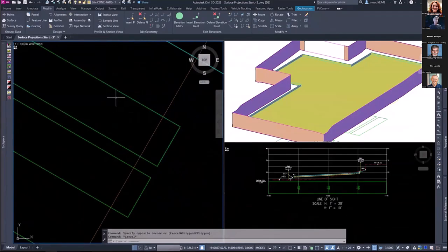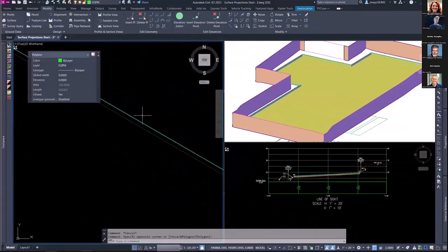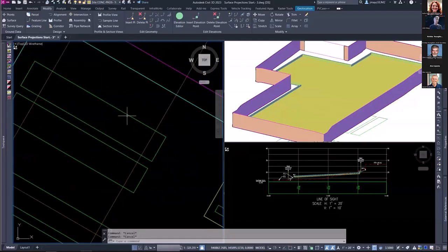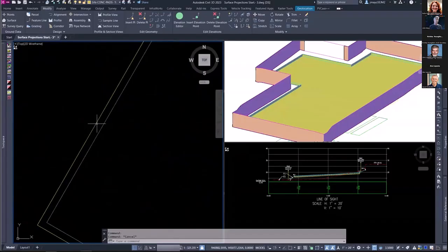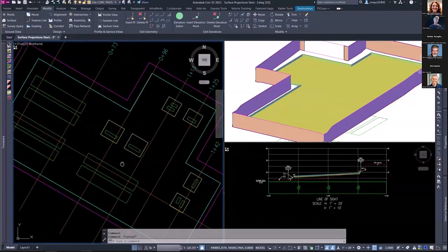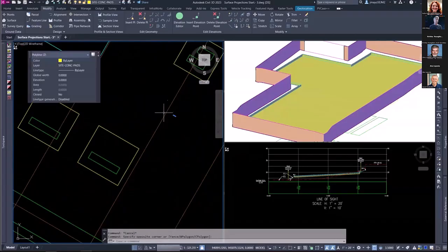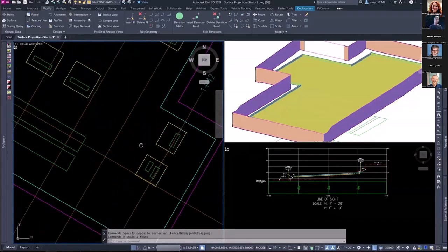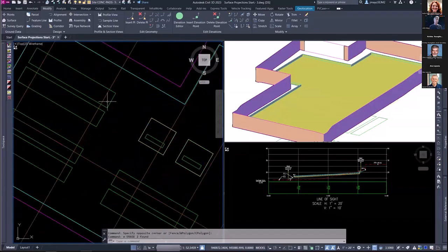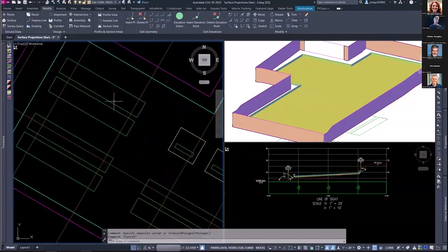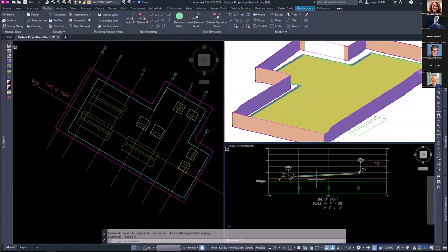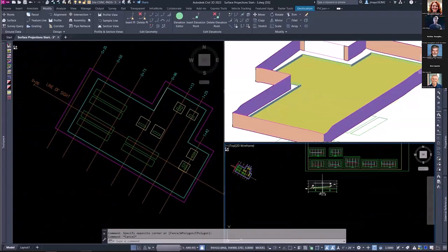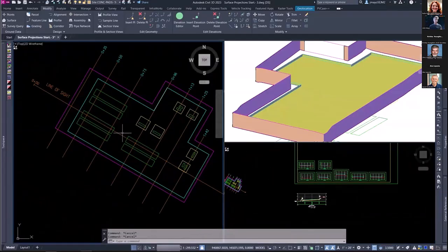And I have here two polylines on different layers, one representing the bottom of the equipment and the other representing the top of the equipment. And I did the same for the concrete pads top. And again, we use a slight horizontal offset to prevent any vertical faces from appearing in the tin. So there we have all those objects, and I did that prep work just to make this process easy, but we can very easily make a surface of all of that equipment and bring it up to grade and automatically project it all into these profiles or cross sections very easily and fast.